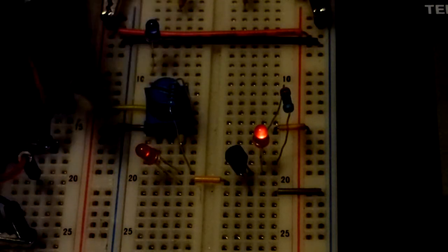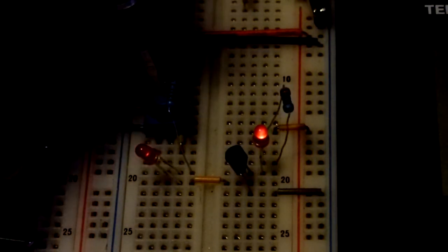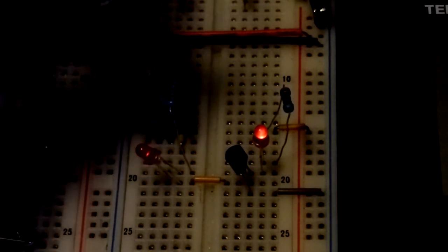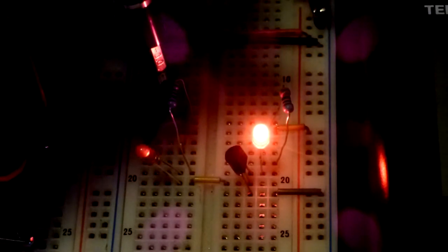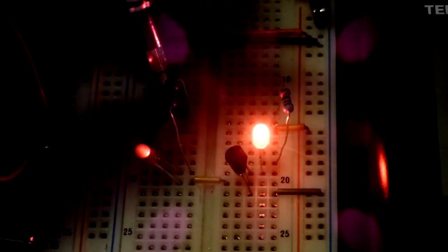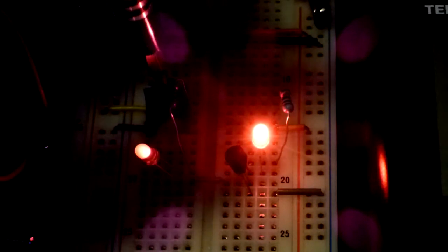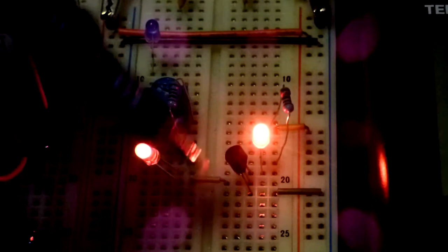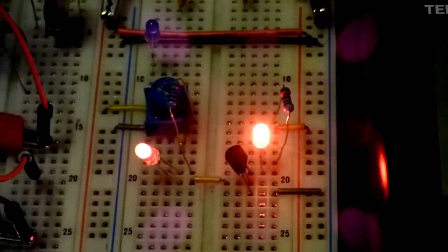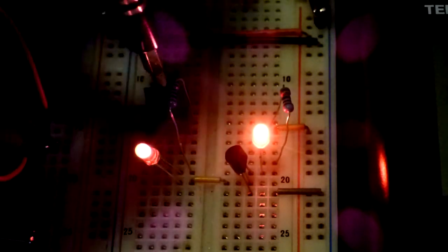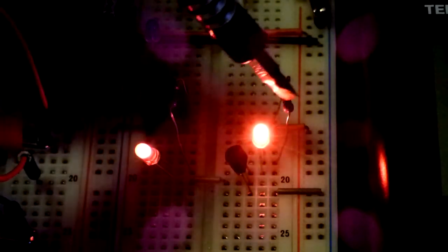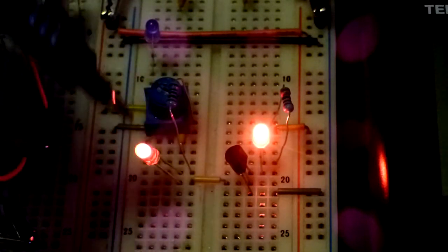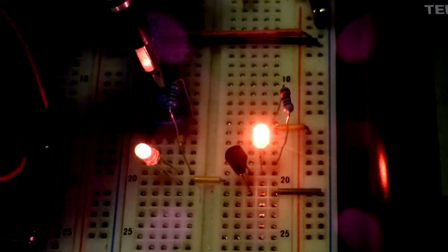A lot quicker. There is a little bit of current going through that one, but not enough to really get it to light up. I'll turn this up a little bit more once I get back in the slot. And there you can see a whole lot more current is going through the collector to emitter than the base to emitter. At some point, it's going to stop getting brighter. The transistor is going to conduct as well as it can. The resistor and the LED will limit current, and that one will get a little bit brighter. But in any case, there you can see it's a 220 ohm resistor. It's letting more current go through than the 1 kilo ohm for that one. So that's the main thing.